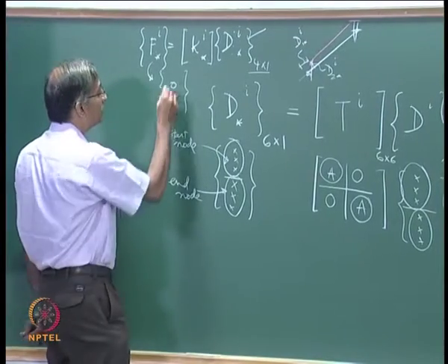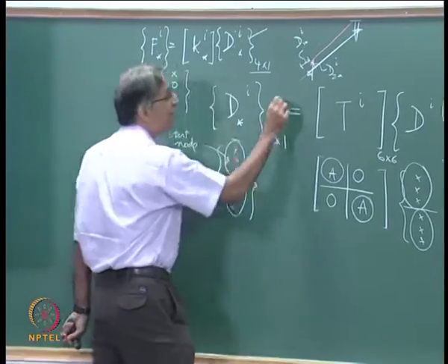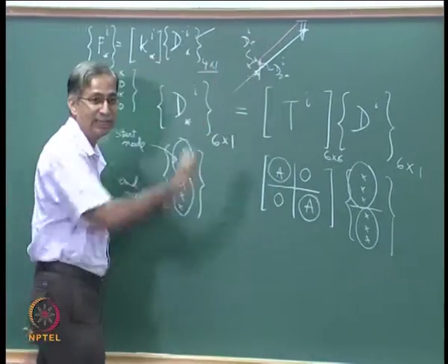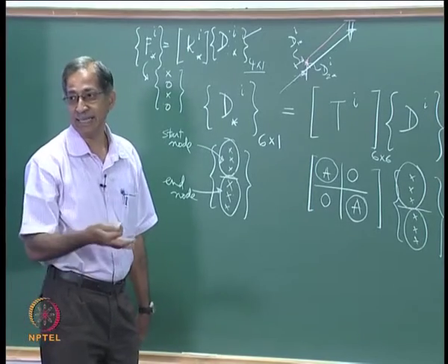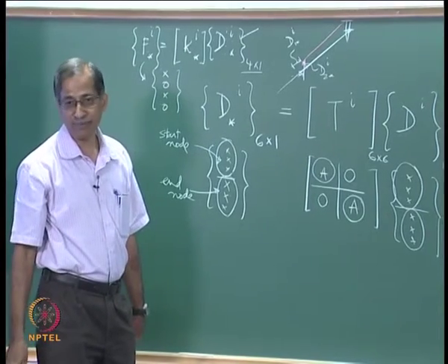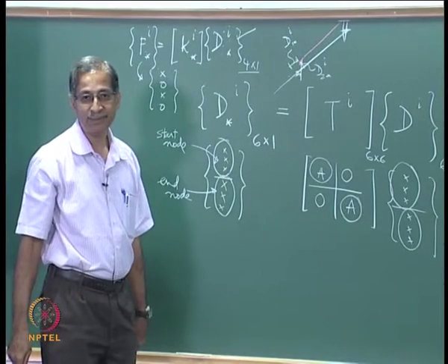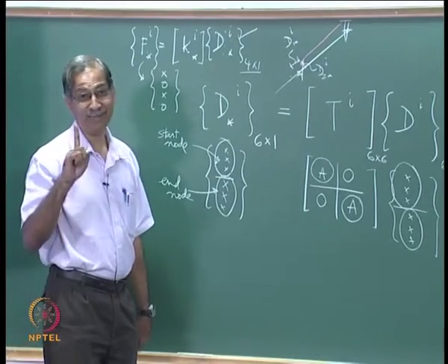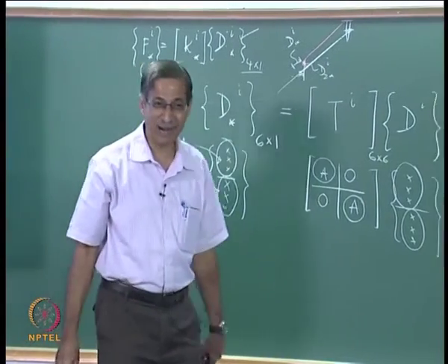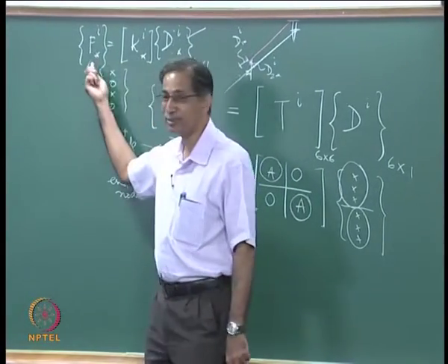And even worse, these two are not truly independent because the resultant of them must be aligned along this direction. Is it clear? So we will see it is related to the rank of the matrix. What is the rank of the stiffness matrix? It's 1. So you can see that this can be reduced to 1s.